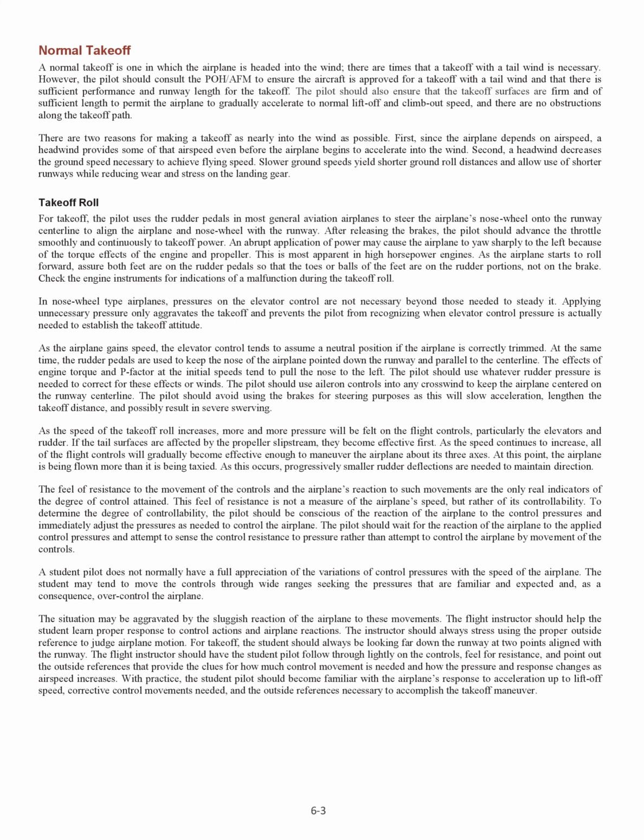The pilot should also ensure that the takeoff surfaces are firm and of sufficient length to permit the airplane to gradually accelerate to normal liftoff and climb out speed, and there are no obstructions along the takeoff path.